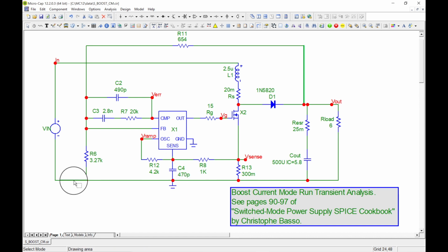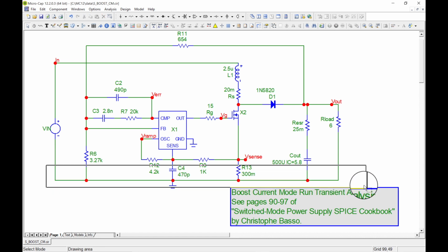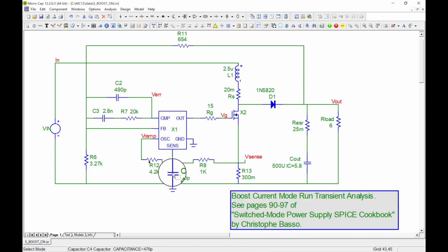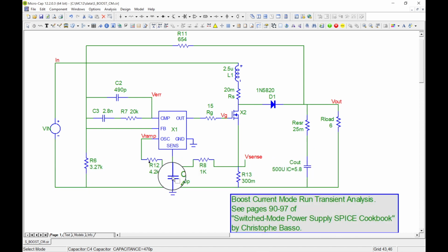Okay, now look, here's two more four ways. This one here, they're so tight. See how I hover over the line, how it highlights it, but see how short that line is? So I guess I could drag this up there and it would break that four-way. But I just want to give a little more room. So here's another thing you can do: you can hold your mouse key down, and when you go like this, whatever you're touching is going to be selected. So then, now I might pull this text away from the resistor. Let's see if it does. I'm going to click down and pull. Yeah, see, I'm not moving the resistors. So, all right, I'll just have to go back and grab them, I guess.